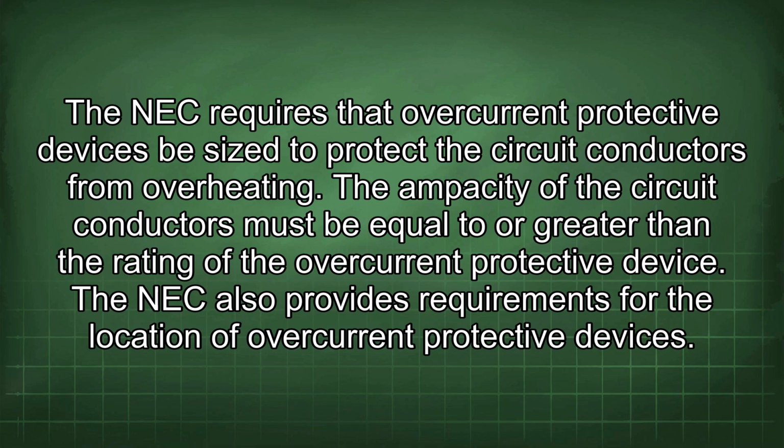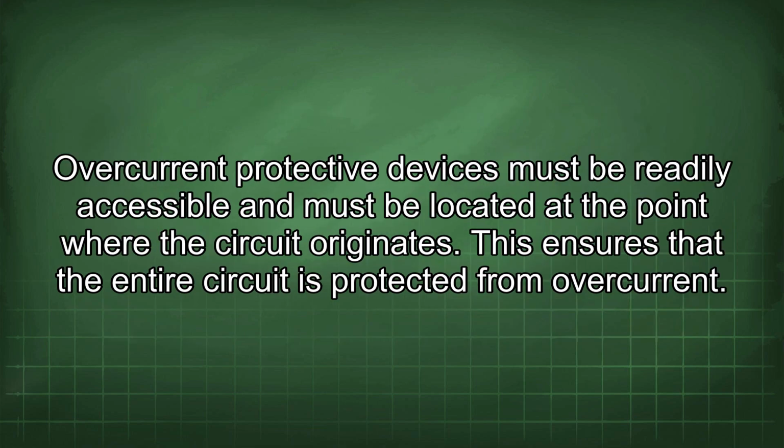The NEC also provides requirements for the location of overcurrent protective devices. Overcurrent protective devices must be readily accessible and must be located at the point where the circuit originates. This ensures that the entire circuit is protected from overcurrent.